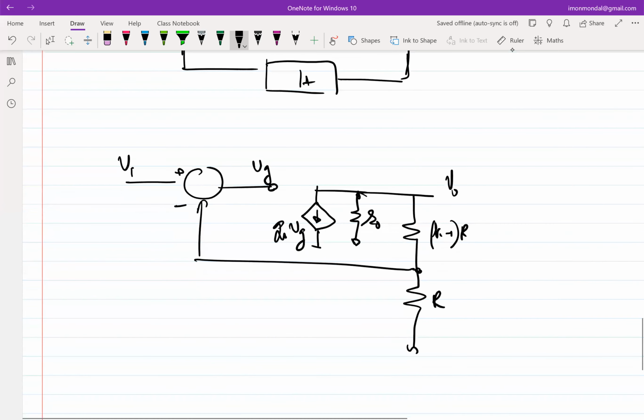Okay. So what is the first test that you need to figure out? The first test is whether the sense of the loop is right. Is it a negative feedback loop or a positive feedback loop? So what will you do? Can you do your analysis and tell me whether it's a positive feedback or a negative feedback loop? And either way, why do you think so? Yeah, why positive feedback? Right. So exactly. Essentially, I can break the loop anywhere, or you don't even have to break the loop. You assume a hypothetical excursion. If this goes high, this goes low, this goes low, this goes low. It goes through a negative terminal, so this will go high. So the loop is reinforcing the excitation, which means it's a positive feedback loop. So this is not going to work. Since we are in a block diagrammatic sense, we can always reverse the signs here. Okay, so now it's a negative feedback loop. Correct? Okay.